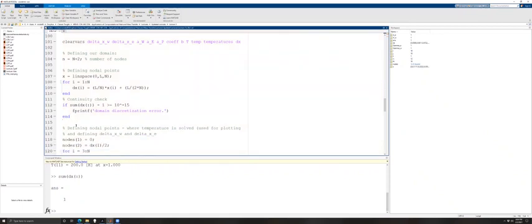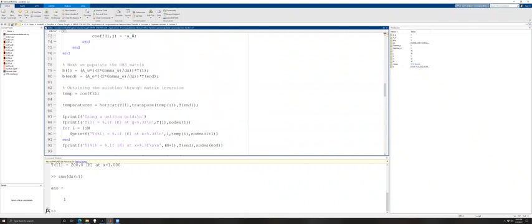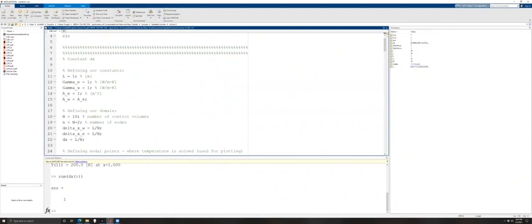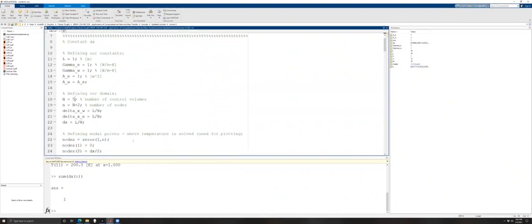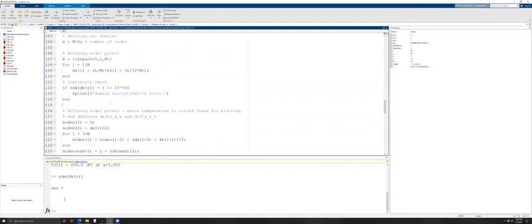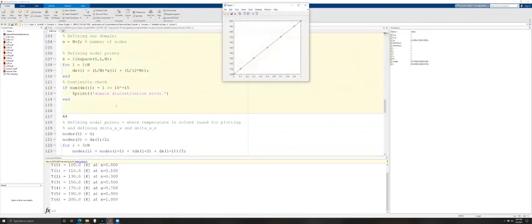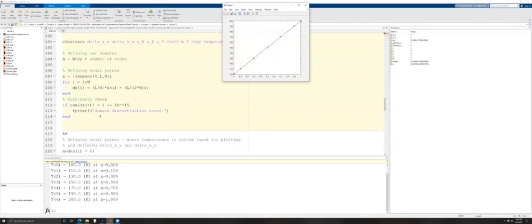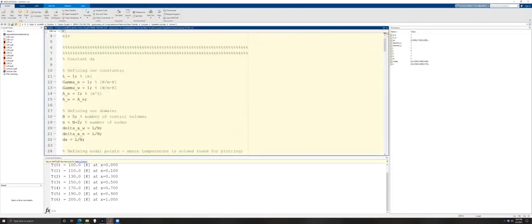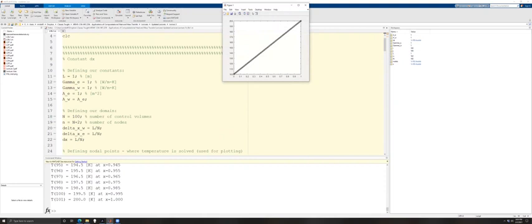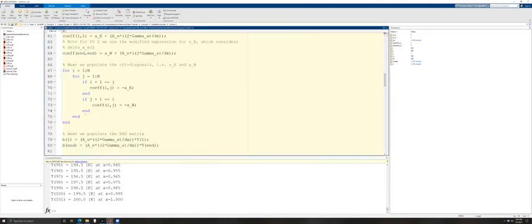So the first thing we have to do if we have a non-uniform grid is definitely specify the lengths of each of our dx. You could do it manually, but I like doing it in code, making it really robust in case I want to change the number of control volumes. Say I set this to 5. It works down here, no domain discretization error. Say we want 100 control volumes. No domain discretization error. It is robust.